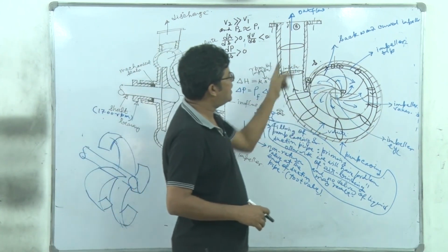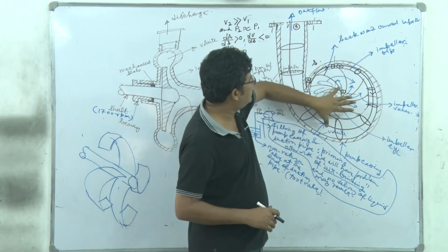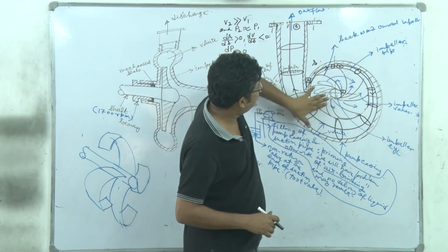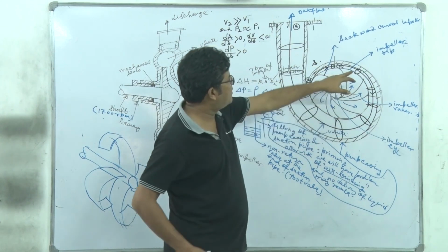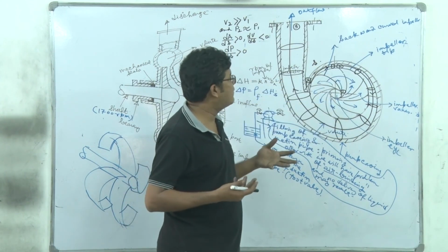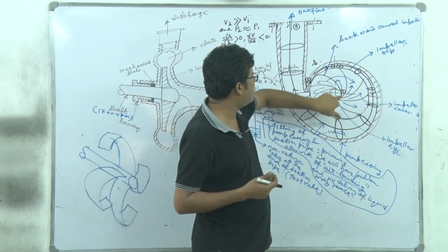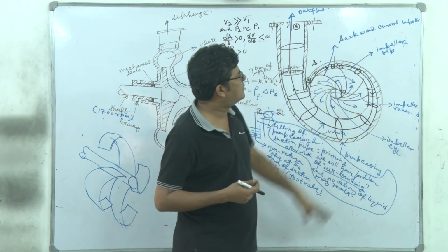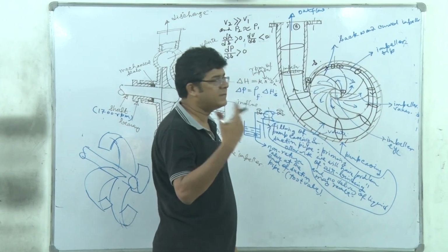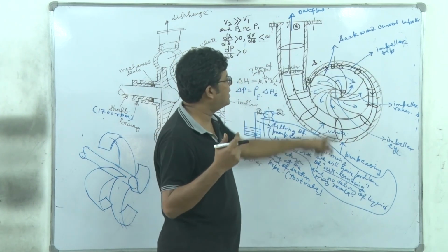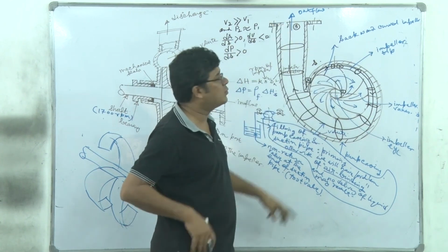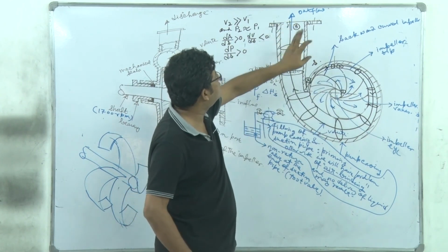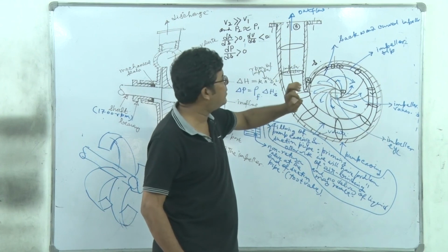Now the impeller starts with a high speed. So fluid, as it is filling up this space, will diverge out towards the impeller tip, acquiring high velocity head or high kinetic energy as it moves from this eye to the tip. Now from this tip, this increased velocity head, which is the primary mode of energy supply, is to be converted equivalently to pressure head as the liquid moves to point 3, which is the pump outlet.